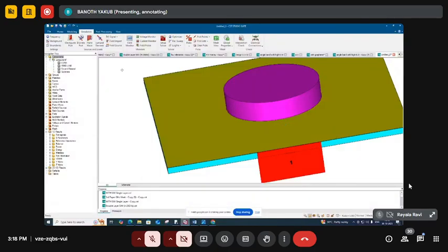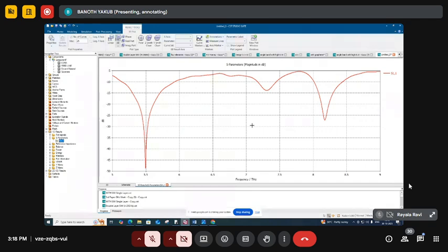The simulation is completed. Now you can see the results. It is clearly visible now. I changed the range to 5 to 9 terahertz, and that operating frequency came here. Is it visible or not, sir? Nice, sir. Visible, sir. These three bands we are also getting here. We can see below minus 10 dB at 5.5 terahertz, at 7.3 terahertz, and at 8.3 terahertz. We are getting three bands in this operating frequency. So our antenna design is getting good results in the terahertz frequency, with three bands.